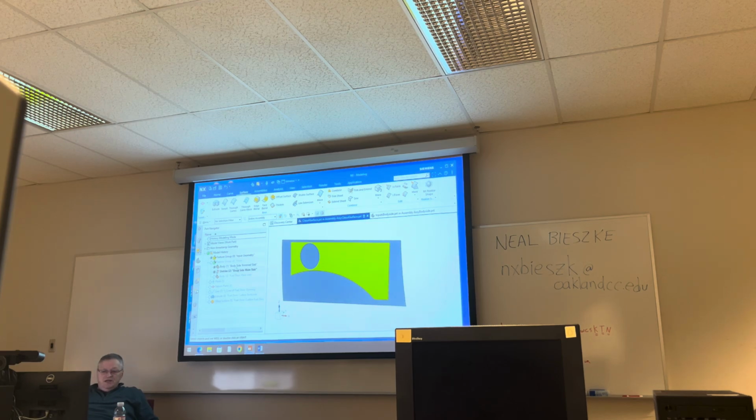So then it says, now that I've done that in the work part, I'm also going to update to the end, well, they don't call it that anymore, now they call it make last feature current, okay? Then it says to save it, this time it does say save the work part. So I'm implying, just go up here and hit this save, okay? Because I am actively inside of just one part in the assembly, and that's all I modified, and I did make a change, so I did save it, all right?